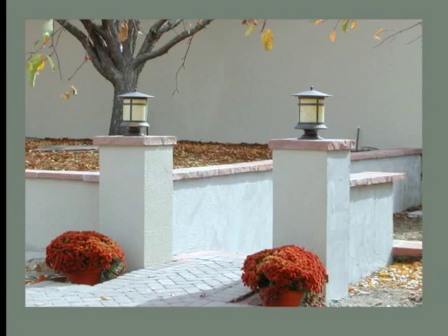So the other veneer we can apply to walls is stucco. Probably the least expensive of our veneers, because it's just easier to put on. I always worry about how it's going to hold up in the landscape. And I don't like to use it anywhere people are going to be walking close by, kicking it. I think it'll get messy looking. Notice on these walls, do you see how the top, the coping, overhangs a little bit? I think that's an important design detail because that allows the water to drip off, especially on stucco, so that the water doesn't run down the face of that stucco and make stains.